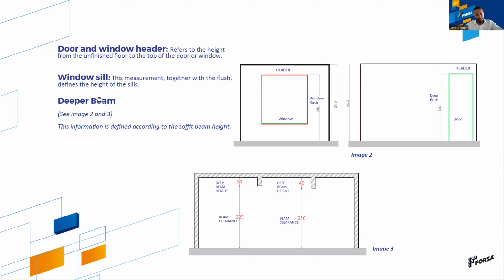And finally, this beam, which means at the end of the day, the beam height itself, is going to be pretty useful if you try to keep it at the same height, or if you change it between them in similar distances and close numbers. For example, as we have here 30, we have here 40, we have these measures in centimeters. I'm going to make that clear. We have here 30 centimeters, we have here 40 centimeters, and all those are pretty important. And the changes are like 10 centimeters between them.